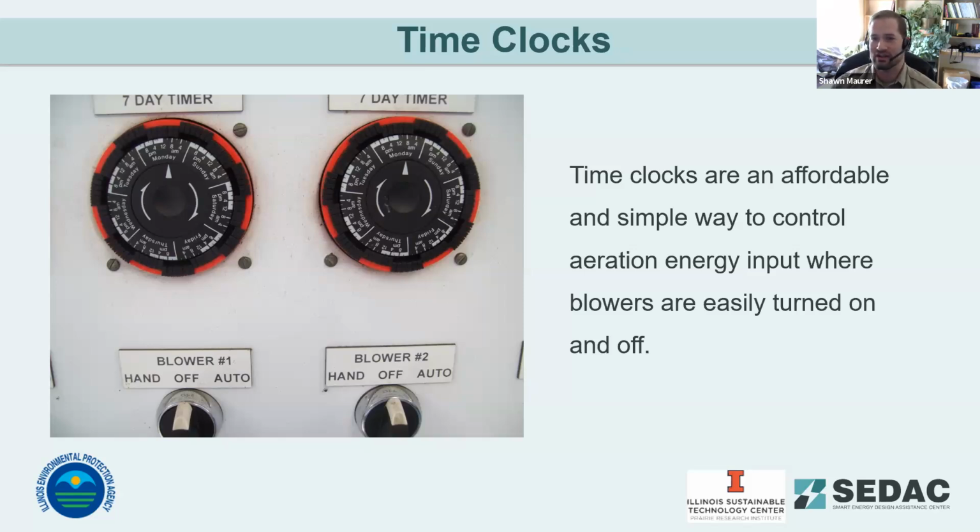In the evenings when you're getting a large loading coming into the plant, typically with people coming home from the office, they're starting to shower, clean, do dishes, and so on at home, you get that evening surge in loading. Then you might need to ramp the system up, and then overnight, as people have gone to sleep, you don't have that loading, you can dial back again. Timers can help do that kind of scheduling in your process. But you do need to do some research ahead of time to know what that loading profile in your lagoon looks like.